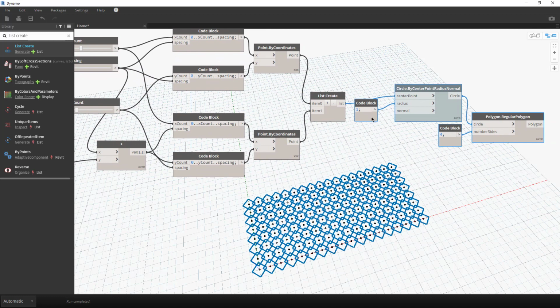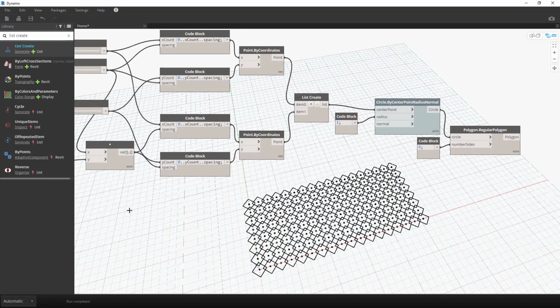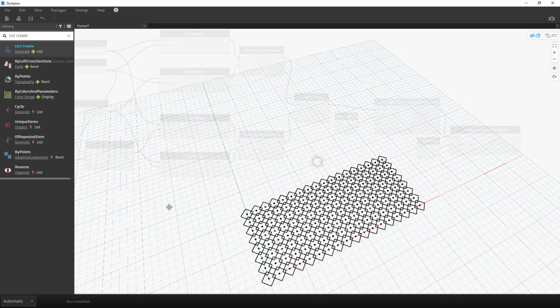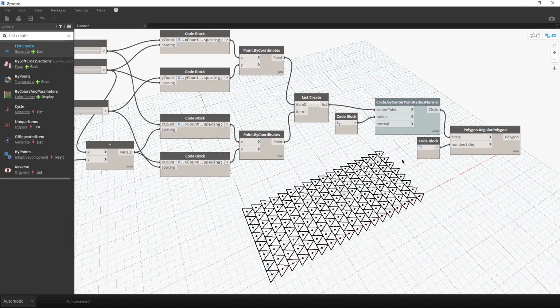And we'll clean up the last couple nodes of this definition to better display what's going on. This basic definition automates the task of creating a grid of diamonds. Navigating the background 3D preview by holding down Escape and repositioning, we can see that as we make changes to any of the number values, those changes are reflected in the background dynamically.